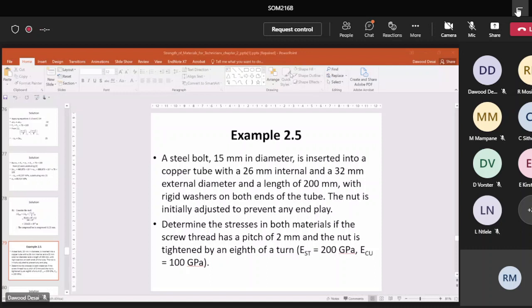If you click on your solution now, you cannot spend much time on mathematics. If you look at your solution, you can see over there, just put your 300. They're using area is equal to load upon stress, making subject of the formula. You can get an area there. From the area, you work backwards, you end up with 2250. You're working in millimeter square. That must equal pi d square upon 4. You make diameter the subject of the formula, and you get 53. So I think that should be very, very simple. It's just mathematics. I cannot teach mathematics. This is really grade 5, grade 6 work in school, making subject of the formula.